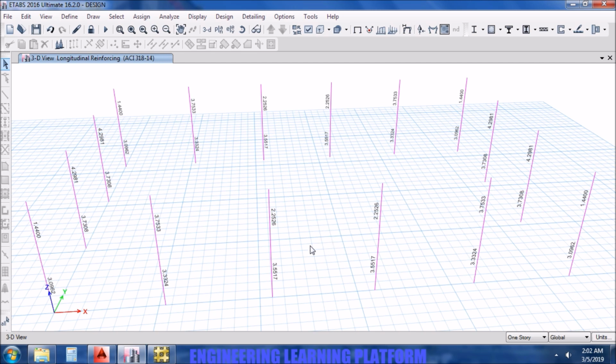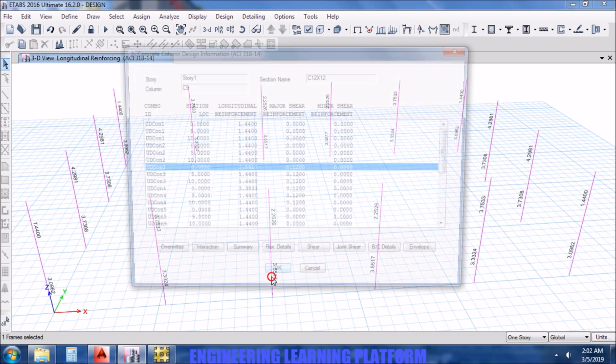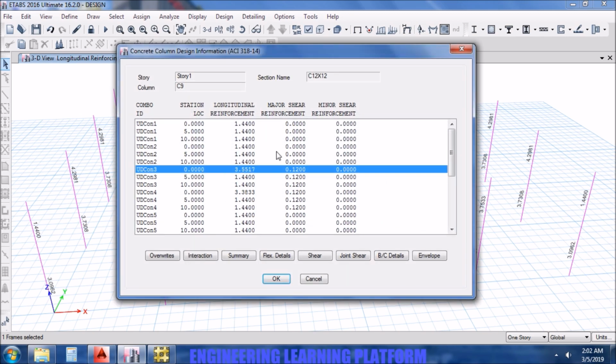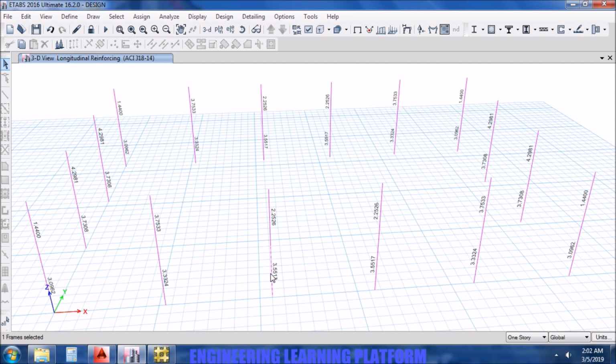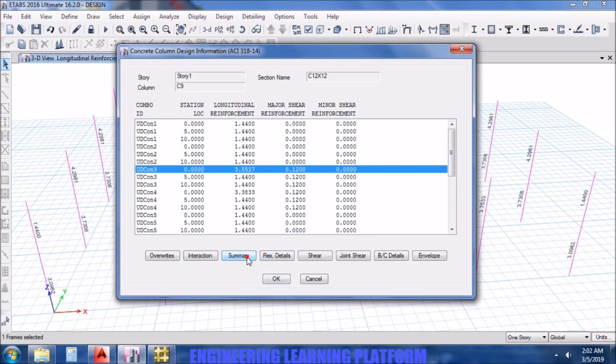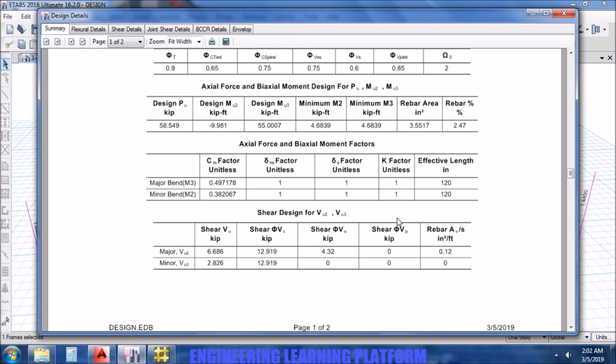So now the percentage of steel is reduced, where Etabs was taking 10 by 10 as default section. Since the properties are overwritten and the forces may not be transferred according to the 12 by 12 cross section as we didn't reanalyze. So usually we need to rerun the model.